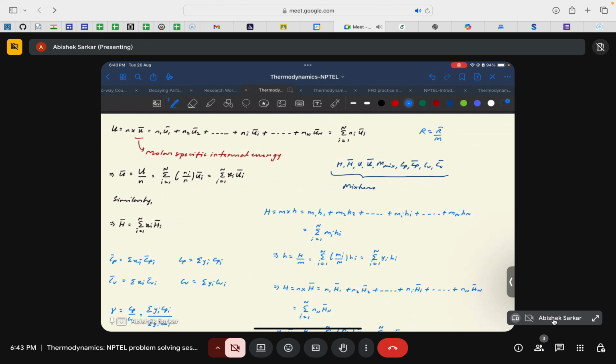Similarly, if you are dealing with air, which is itself a mixture of gases, or any specified mixture of gases, then the specific gas constant for that mixture would be the universal gas constant divided by the molecular weight of the mixture. That's something that you need to remember.